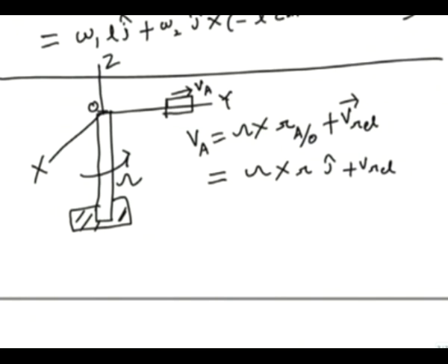And this absolute acceleration will be omega square R J plus twice omega VL I, where 2 omega VL is the Coriolis acceleration, and that is what happens. So these equations which we discussed can be used for three-dimensional things also.